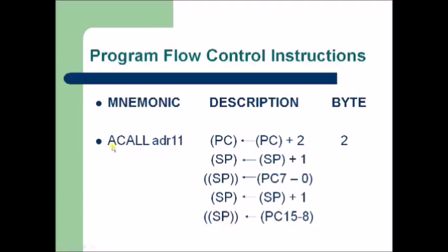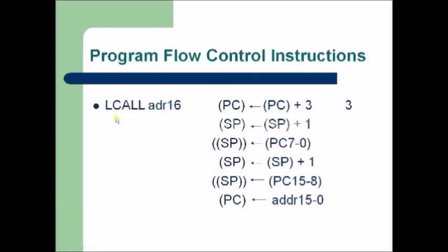Okay, so as we have called a subroutine from the main program, control will be transferred to the subroutine. Before the transfer, the program counter value will be stored inside the stack. This particular storage inside the stack is called the return address. We are storing the return address. LCALL is nothing but long call, and here the address is 16 bits.